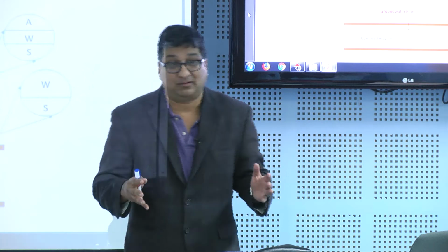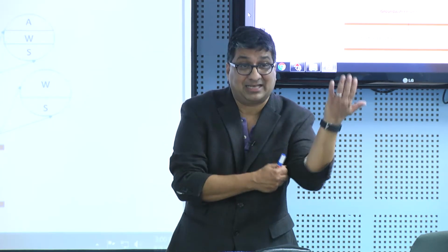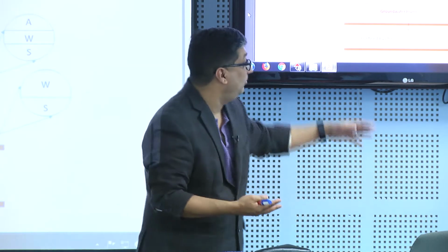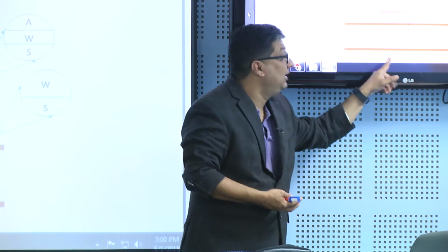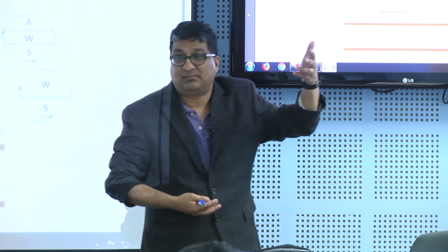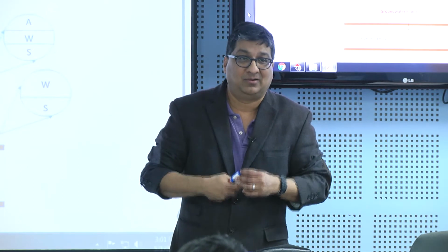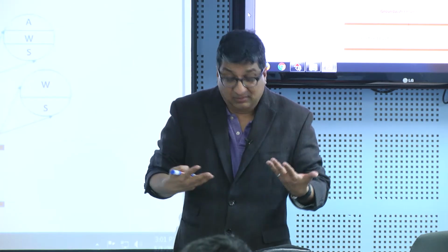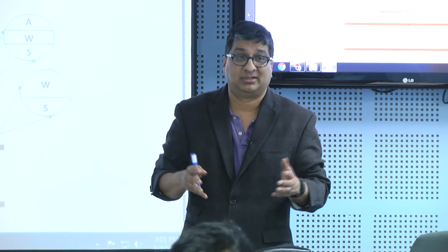So there is a class of chemicals called dense non-aqueous phase liquids, or DNAPLs. Trichloroethylene is a very classic example. These are organic chemicals that are denser than water. If they are lighter than water, they'll float on the water table. If it's denser than water, it will actually penetrate and go inside. And as it goes inside, some of it might get trapped in these confining layers. Again, we don't need a lot, because the concentrations at which we are worried about our health are very, very small. Okay. So it will sit there, slowly bleed into water, slowly bleed into water, and we have spent billions of dollars in the US and many parts of the world trying to get rid of DNAPLs.